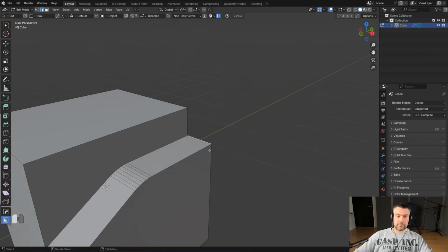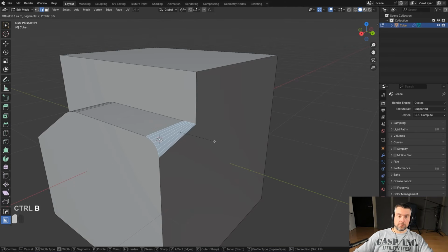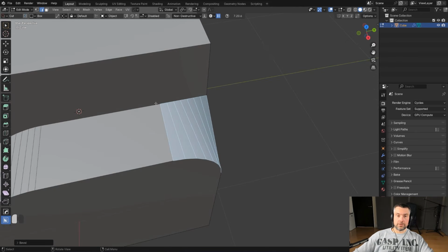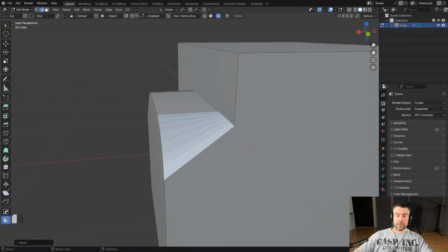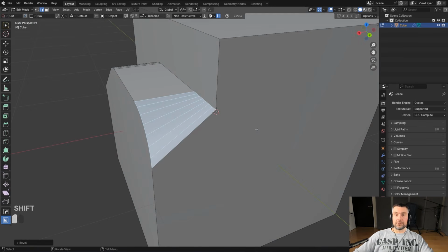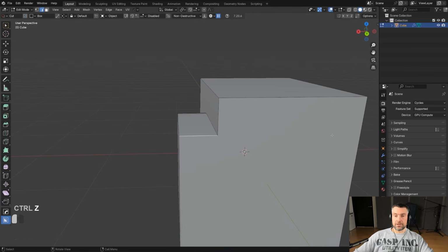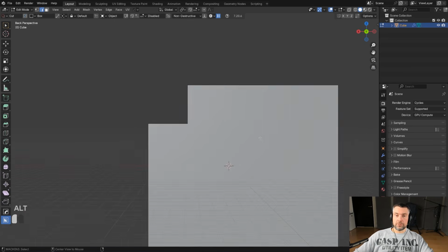So I wanted to curve it in the same way as it's curved in here. I can't do this because when I go with Control B, you see this happens, right? The bevel is being run along this edge here, and this edge is being beveled properly, but this one doesn't have anything to run on, doesn't have any edge to support the bevel. So what you need to do is add an edge here in order to have a guide edge to support the bevel in this corner. So you would need to create a straight line.